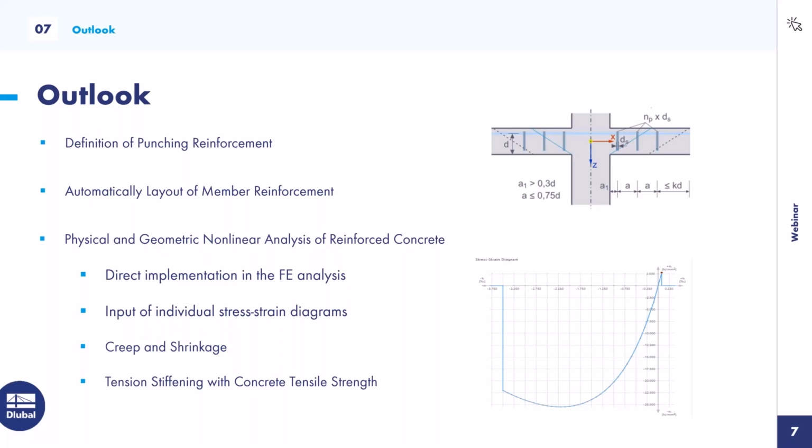So it is possible to use the nonlinearity of the reinforced concrete together with other nonlinear materials, or for example other add-ons like the nonlinear pushover analysis and so on. This is one of the biggest improvements in comparison to RFEM 5, where the nonlinear reinforced concrete calculation was an isolated calculation in the add-on RF-CONCRETE Surfaces or RF-CONCRETE Members, for the participants who already work with RFEM 5.